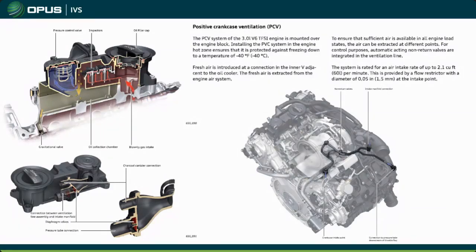Now, I haven't seen a lot of these engines with issues, but I could tell you from experience where I would think we're going to have issues. And of course, the first thing I'm going to say is this pressure control valve, the diaphragm here. I'm sure that they're using this updated material with the fiberglass woven material for strength.